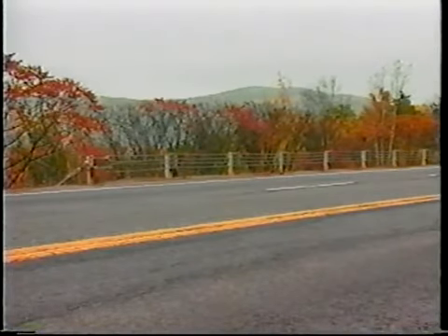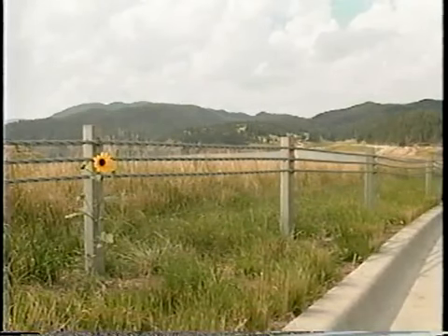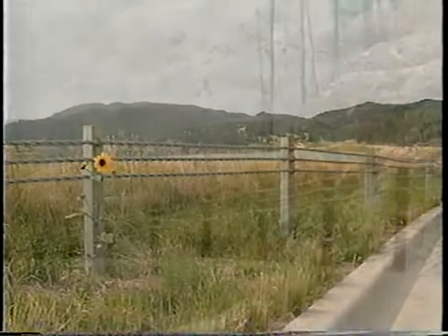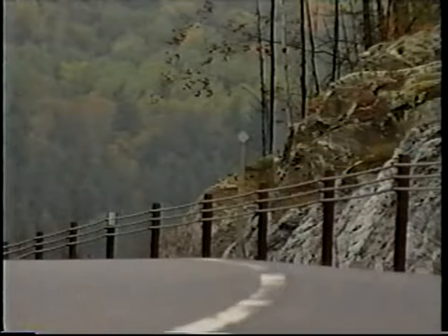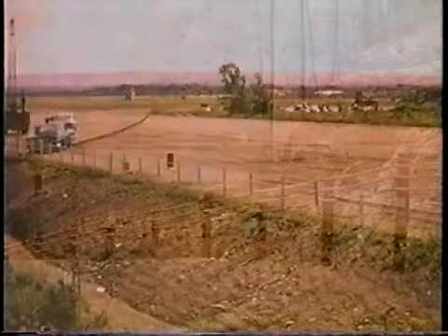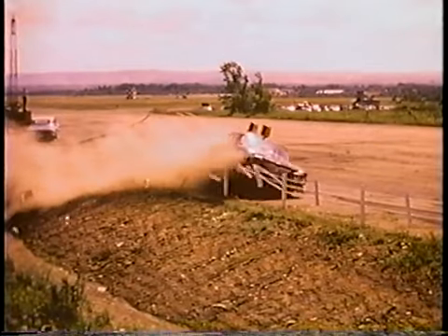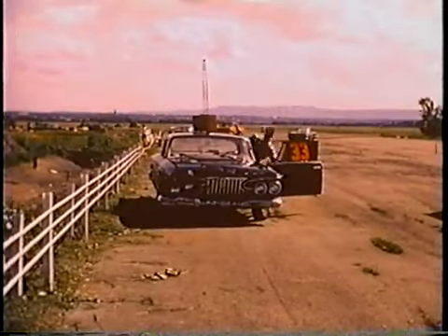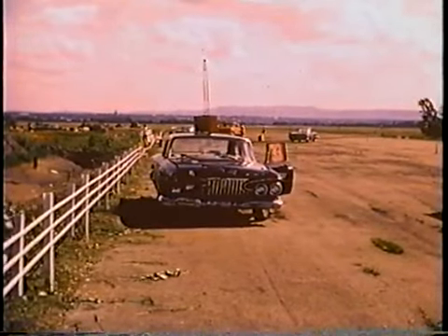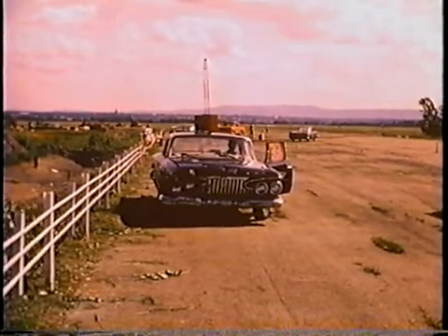Although there are a variety of cable guardrail systems in use today, they all share a number of similar characteristics. The AASHTO Roadside Design Guide designates the most common cable system as the G1 guardrail. It was developed by the New York Department of Transportation in the early 1960s. When correctly used in appropriate sites, the G1 guardrail has proven to be a very forgiving barrier system.